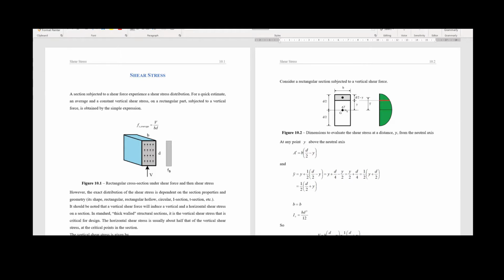We saw this in part the last lesson in combined stress, because in combined stress we have a combination between this axial stress, very simple, plus the bending stress, which is a little bit more complex because of the moments that the bending produces. There is a linear distribution of the stresses from a maximum in compression to a minimum zero at the level of the neutral axis, and after a linear increment until you reach the maximum in tension, for example. But there are more stresses.